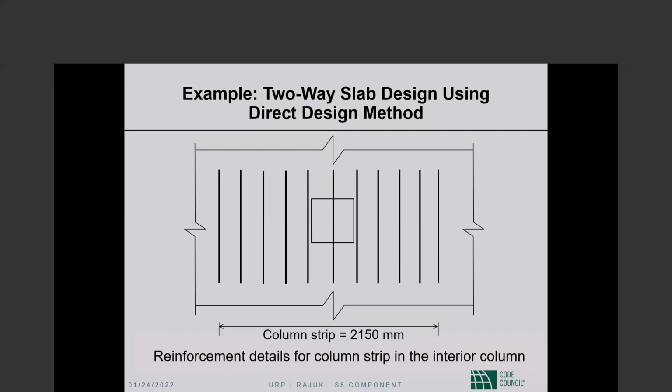Can you analyze it like conventional beams? I do not see why you will need to or want to. The main consideration will be the development of the bars beyond the opening. And if the thickness is the same, why would you want to analyze it?